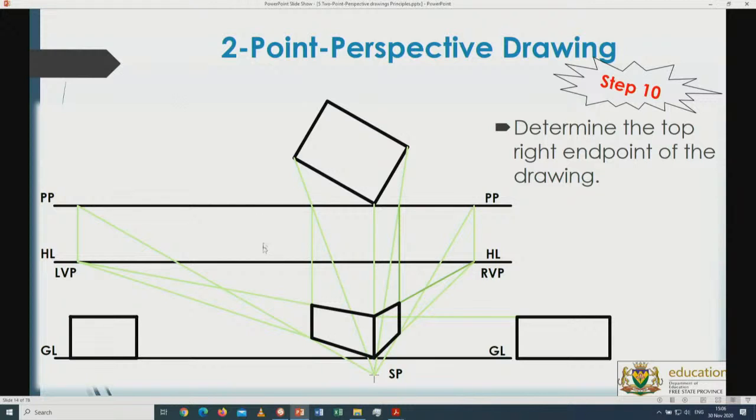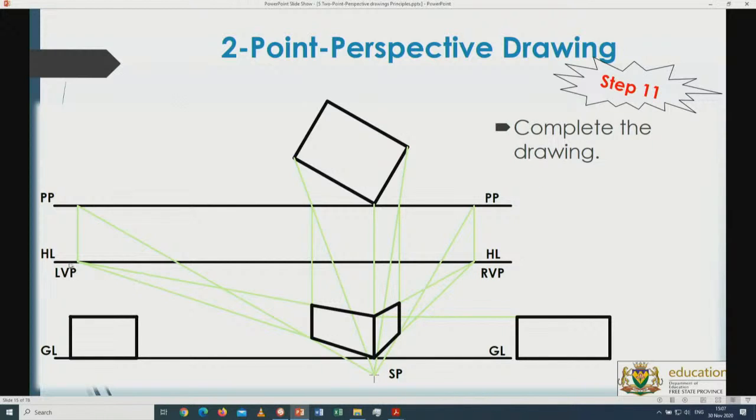From there it goes downwards until it reaches the height, which is that height over there, and that will disappear to the right. So that line over there will also be going through this point, and where those lines, the first line and the second line, intersect with each other, that's going to be the end point of this drawing at the top. But now you've seen it goes through this point, so the shortcut in this case is where you take that line, extend it towards the left, and you take this line and extend it to the right, and that will give you the intersection point to end the block over there. So that's the easy way.